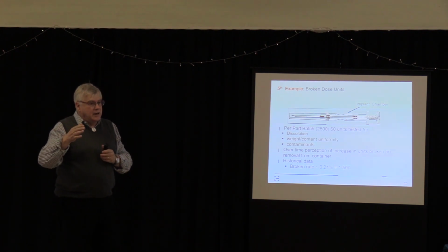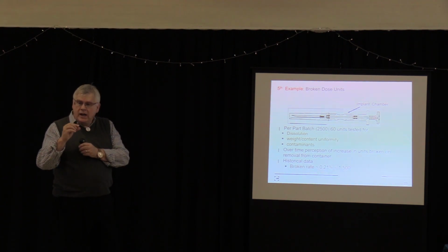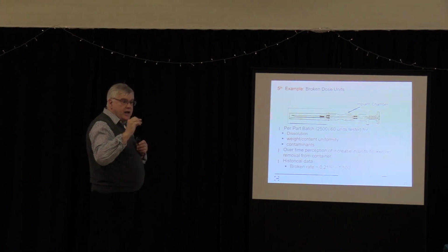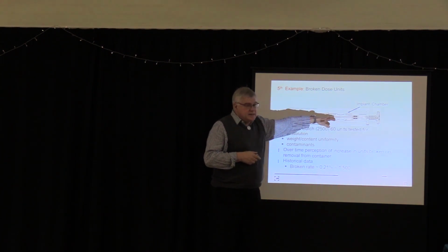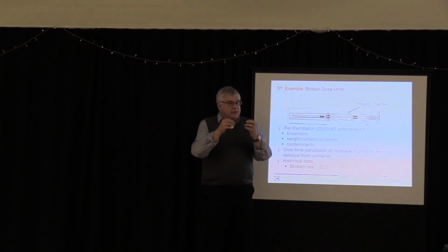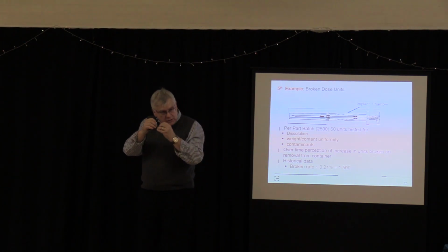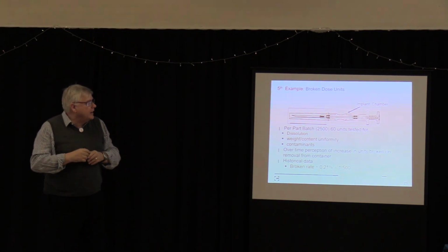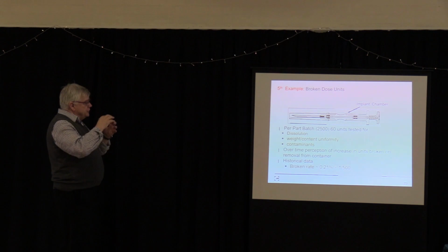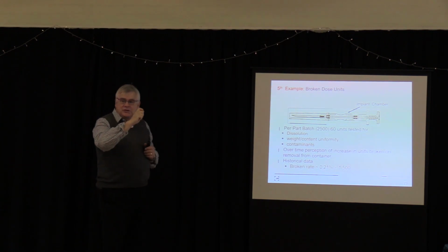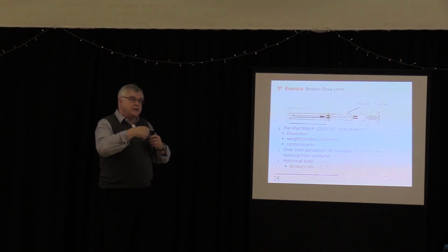And what was happening was they weren't controlling the diameter of the extrusion sufficiently well, so that sometimes it was a slightly larger diameter, which when it went into there and it dried, because this was quite sticky at that stage, it would get attached to the inside of the syringe, and then when it was ejected, it would snap.